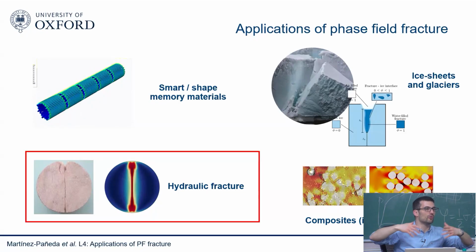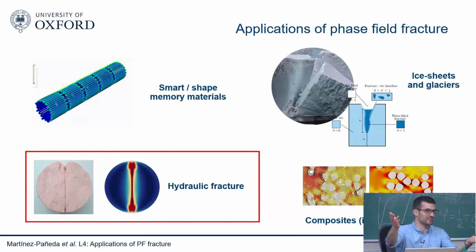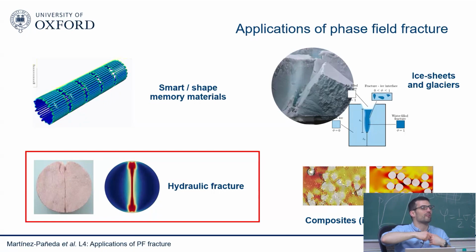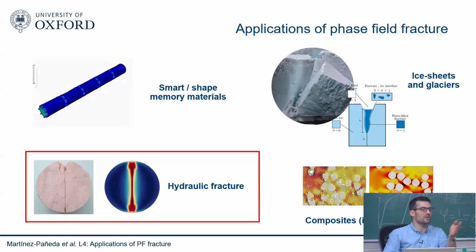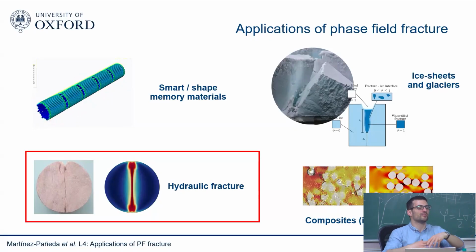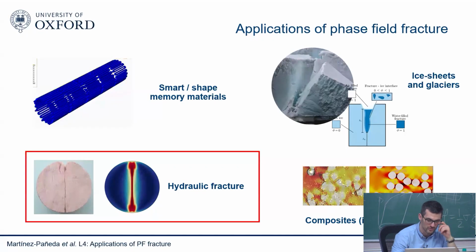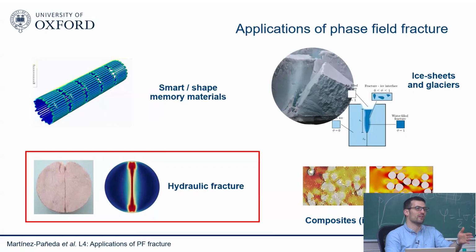However, what we see in these models is that ice is actually behaving as an incompressible material because you have this creep loading. So what we basically say is that our constitutive model captures that naturally, like if you do plasticity. If you have a linear elastoplastic material model, you would define your Poisson ratio at 0.3, but then your material will behave incompressible in the plastic regime because of the constitutive laws. So the same goes here, because you have the creep law, it's going to behave as an incompressible material.